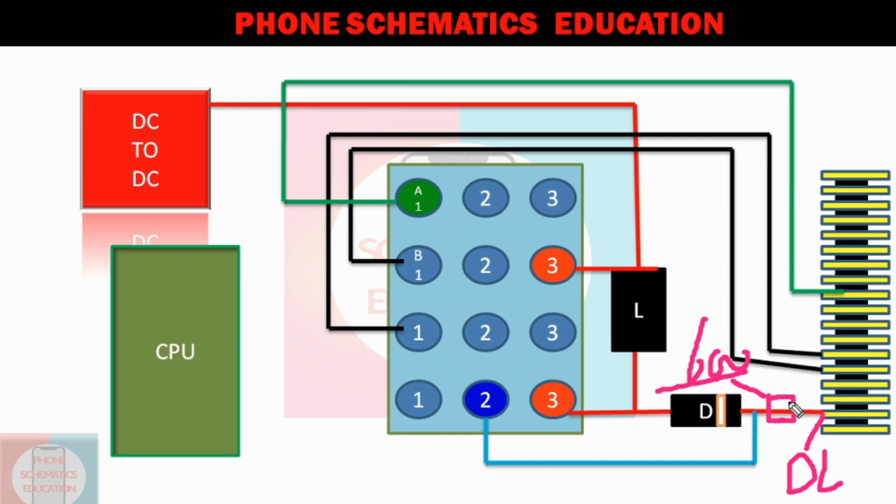Why? When water contacts this connector, from the shorting or high voltage, chances are this resistance opens itself. So there is no connectivity between the circuit, or you can say IC, and the connector. So what do you do?